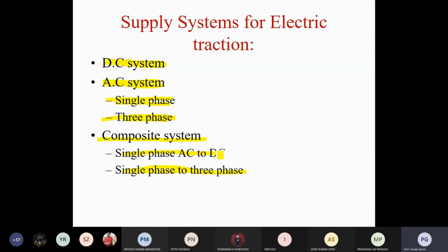Another thing is that some portion of the DC is used for charging the battery. Between the DC and the battery, there is a converter called a bidirectional power electronics converter. Sometimes the battery is charging, so it works in buck mode, and sometimes the battery is discharging, then it works like a boost mode. So it is an example of a buck-boost bidirectional converter. Bidirectional converter topology is normally a buck-boost type topology.